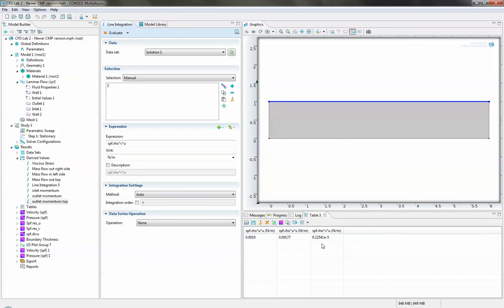What we need to now do, based on the Reynolds transport theorem, is balance the change in momentum flux with the net external forces. Those external forces are derived from either viscous or normal forces. So what we need to do is calculate the viscous shear here.